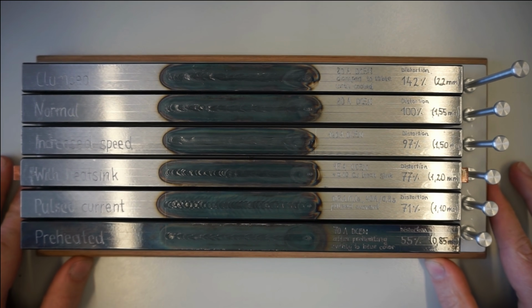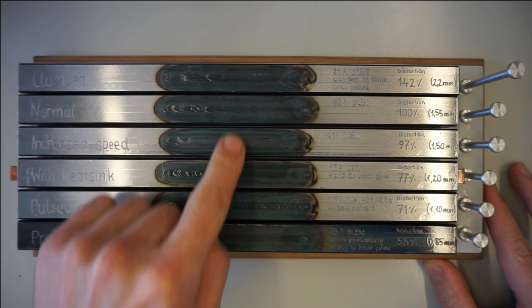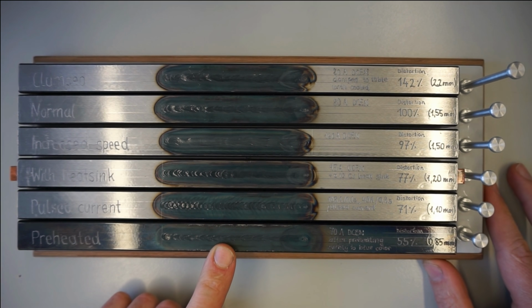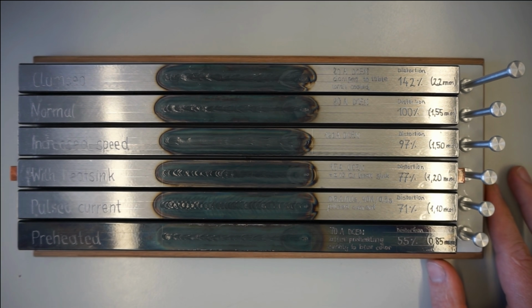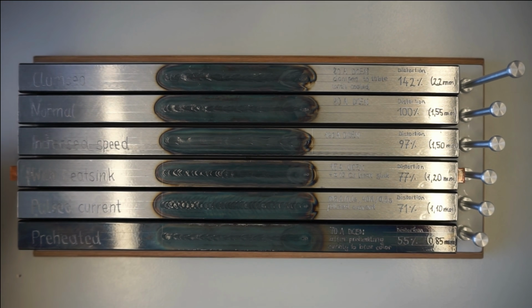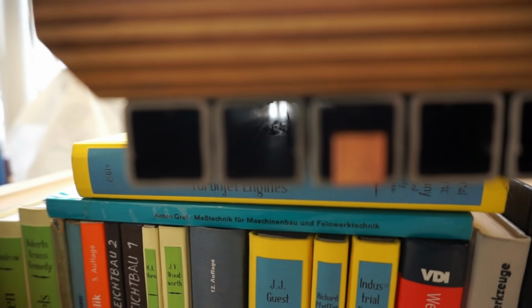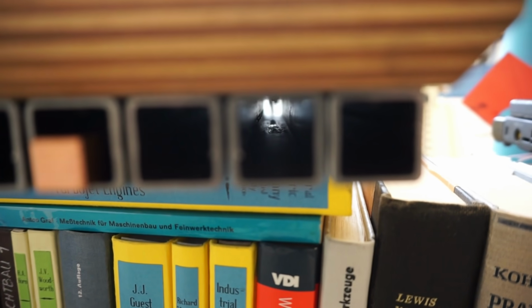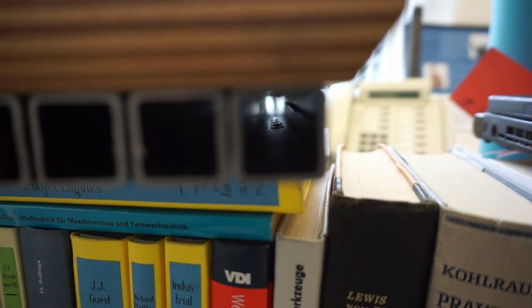First of all, I tried very hard to keep the weld bead sizes as close to the target size as possible. They are not perfect to the 1/10 of a millimeter, but give me a break. Also check the inside of the tubes to see that penetration is pretty similar on all these samples, which ensures that the weld nugget is also of comparable size.